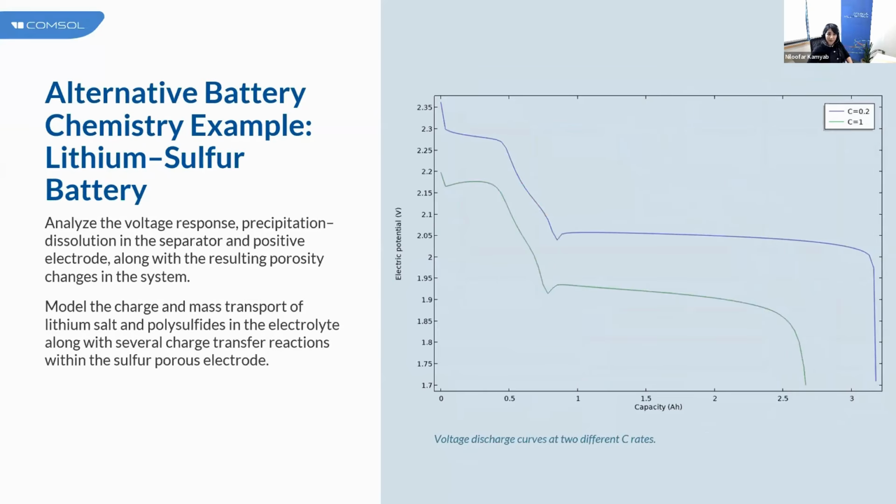Or you go with a complex lithium sulfur battery with a promising energy density that operates a little bit differently from lithium ion battery, because it's not intercalation based, it's a conversion type of porous electrode. But we already know it starts with a very high energy density, but soon, because of some shuttling of polysulfides, it leads to drastic capacity loss, and this lithium sulfur cell has very serious cyclability issues.